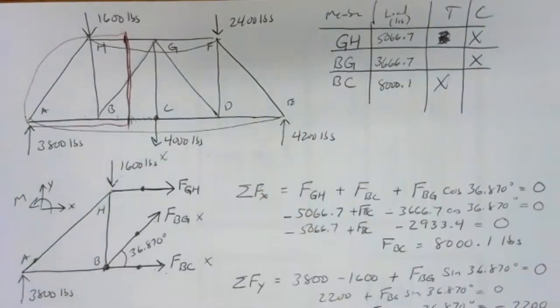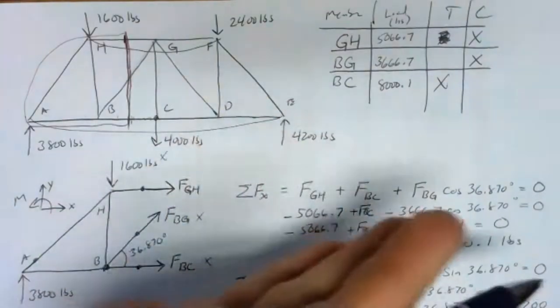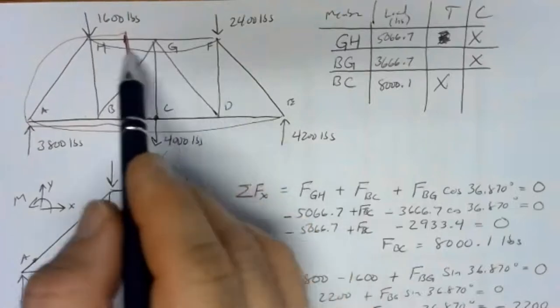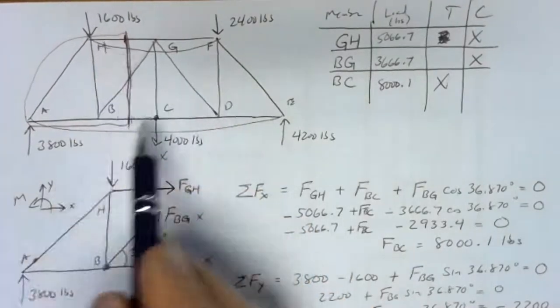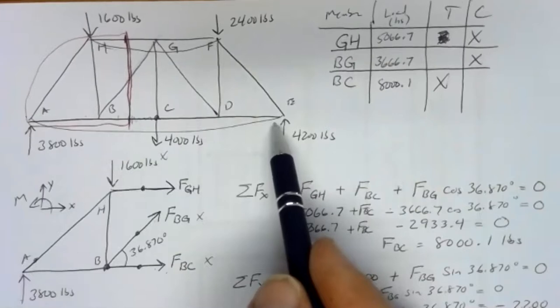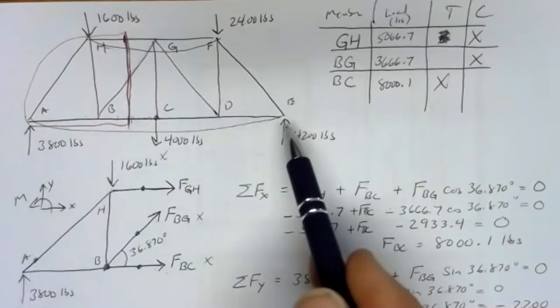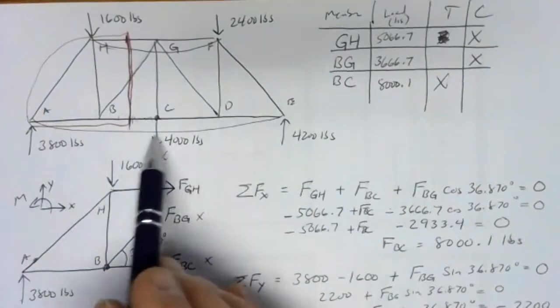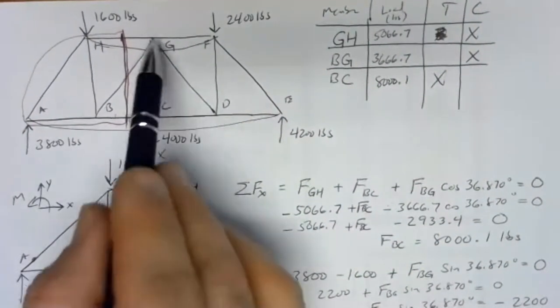When you bend a piece of sheet metal to make it look sort of like that, bending upward on the ends here, you're putting the top into compression and the bottom's getting stretched out. That's in tension. So whether it's a piece of sheet metal or a bridge, it still experiences tension on the bottom and compression on top under that kind of bending load.